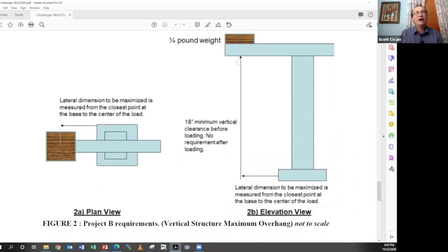But since you're trying to get this to all stand up off of one post, it doesn't have to be one post. You know, this can be anything you want it to be, but you're measuring from the outside of whatever your support is to the weight, to wherever you're putting your weight. And so if you make this wider and wider and wider, you're actually limiting what your actual reach is of this crane thing. Is there any constraint on the width of that platform?